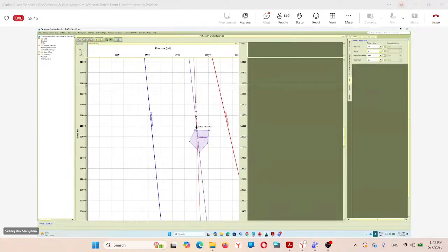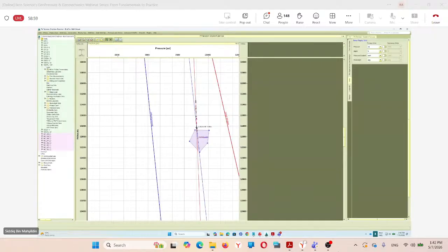I can confirm that with my well data, but I do not have log data loaded over here. I'm sorry about that. So basically, you can bring in your resistivity data next to this viewer and then check how the resistivity looks in comparison to this line, this free water level. Another thing that I could do is put in more wells